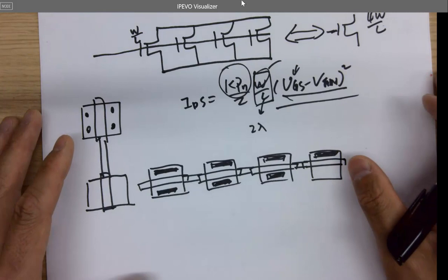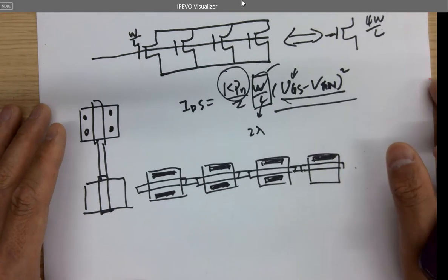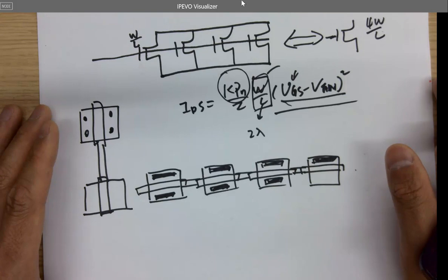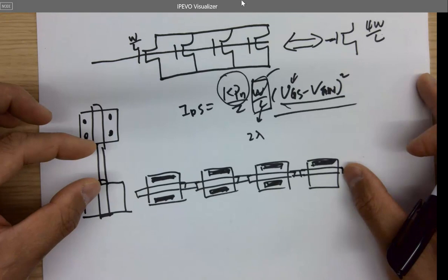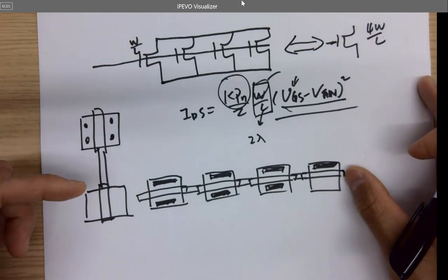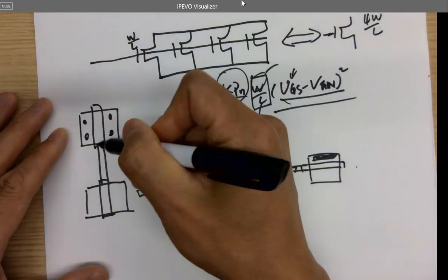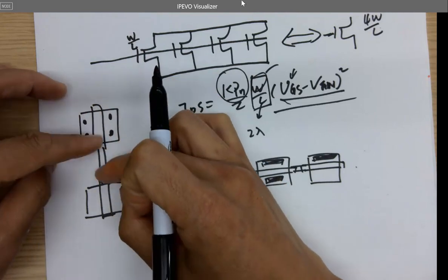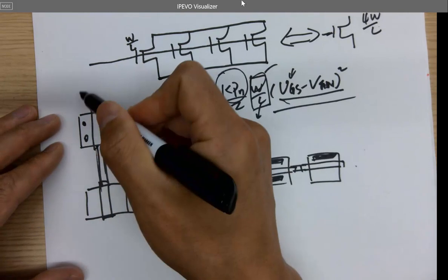Whatever way will make a shorter poly for you, to introduce less resistance in the circuit. So always do it that way, because you can have the 2 gates of polysilicon sticks aligned to each other, so you can directly draw a line here to make them connected to each other. And also for the metal, it's fairly easy as well.